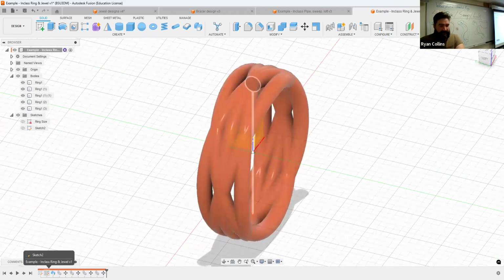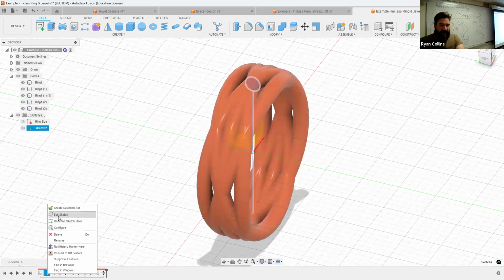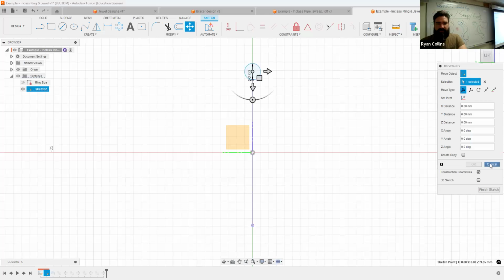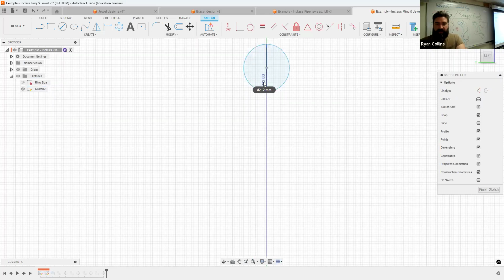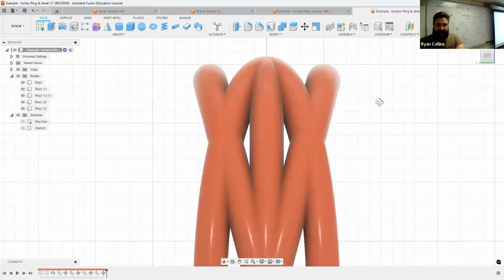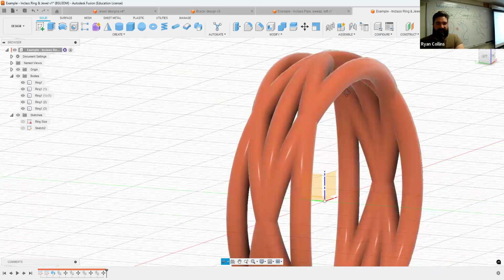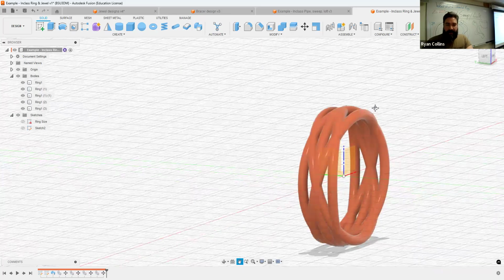So what I'm going to do is go back and edit the original sketch. Let's change the diameter of that original circle. Not move, just change the diameter of the circle. Let's say 1.5. Because the starting point was linked to the edge of that projection, when I hit finish sketch, it recalculates and nothing moved. It just shrank the circle. So cool. Yeah, it's a little bit better defined now. You can even shrink that back down to like 1 or something like that. Too fine, and even that printer isn't going to hack it anymore.